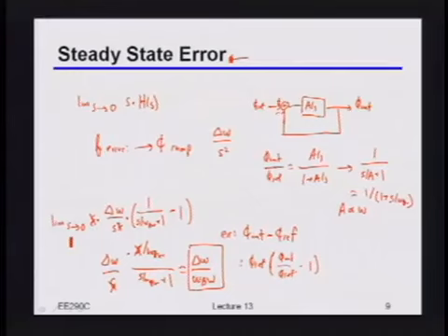So in other words, what this tells you is if you put that ramp into the first order system, that first order CDR, you're going to end up with a static phase error that's basically proportional to the rate of that ramp relative to the bandwidth of your loop.